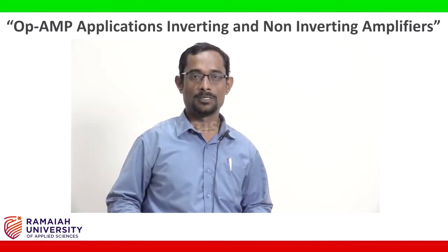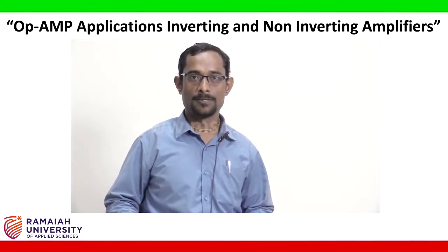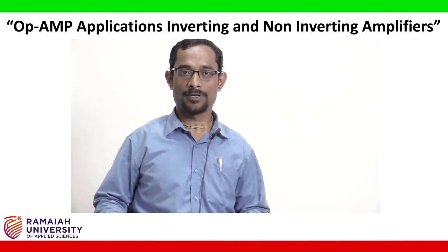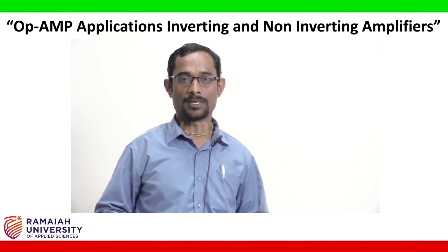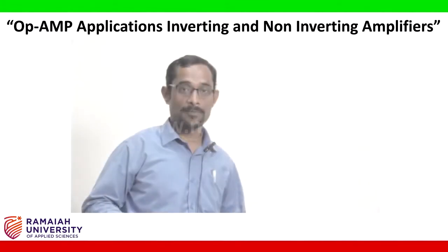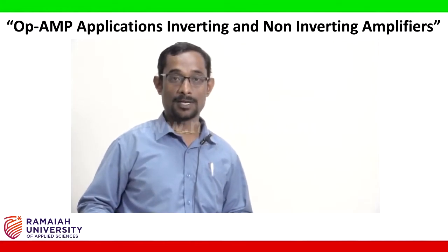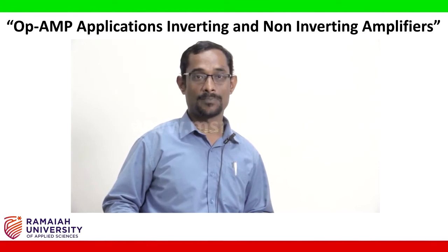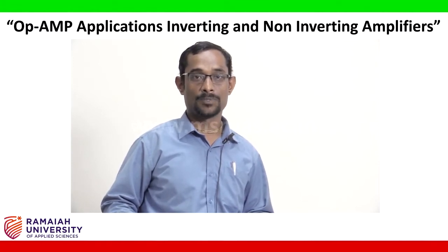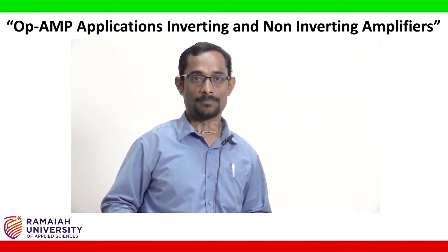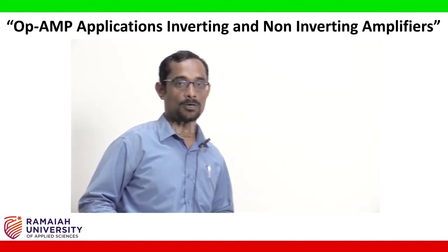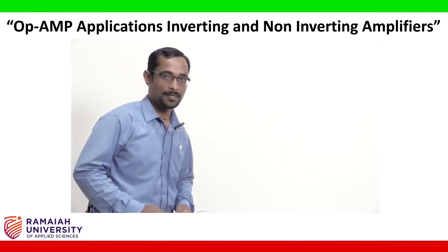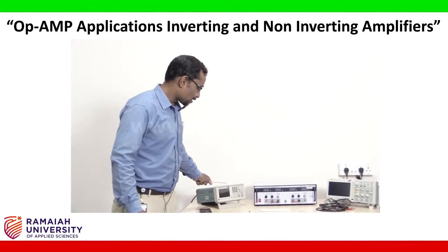Dear students, today I am going to explain the operational amplifier applications for inverting and non-inverting. The aim of the experiment is to generate the waveforms for inverting and non-inverting applications by using IC μA741. Now the components required for the experiment is signal generator.